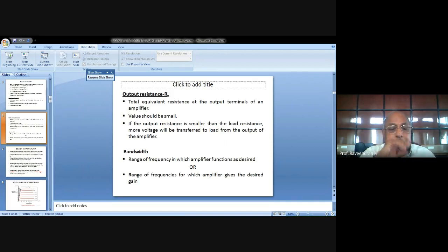Okay. Then what are the disadvantages? The voltage and power gain are low because the effective load resistance of the amplifier is somewhat increased. So I told you, the load means the resistance, or whatever is the load, which is connected at the transistor output here.